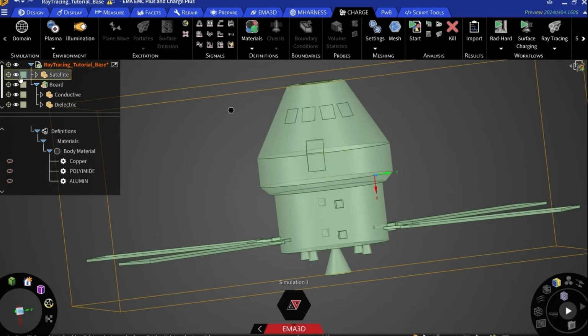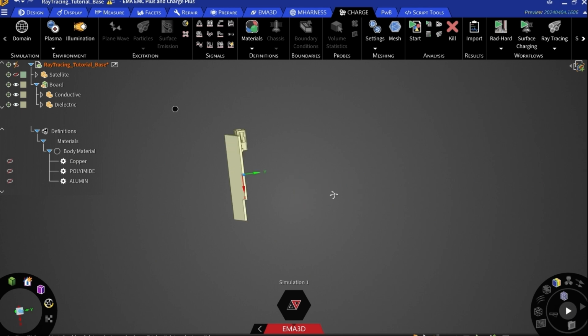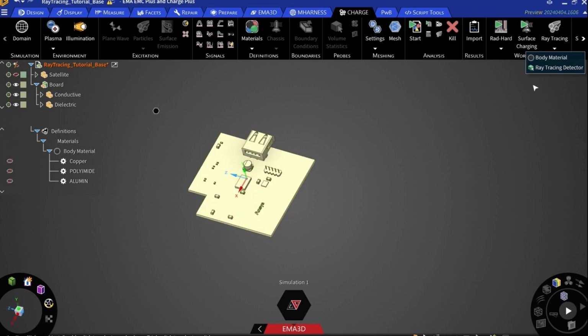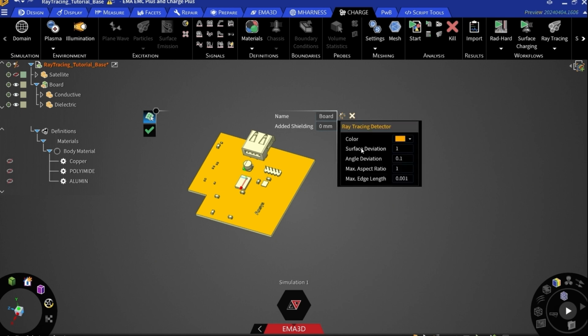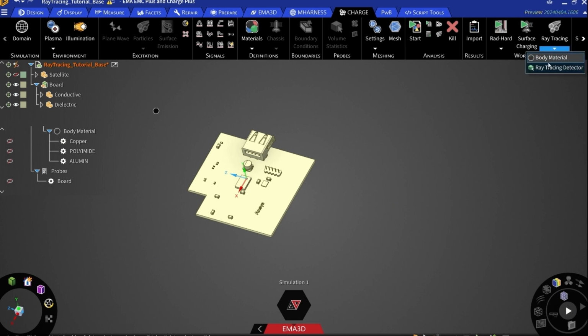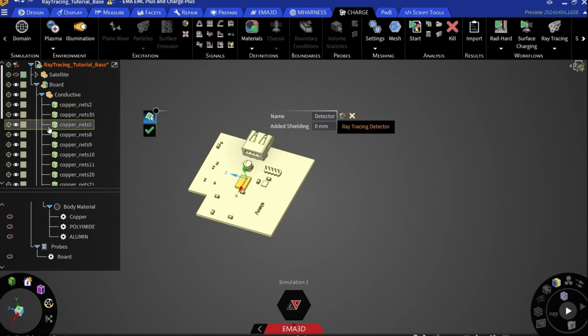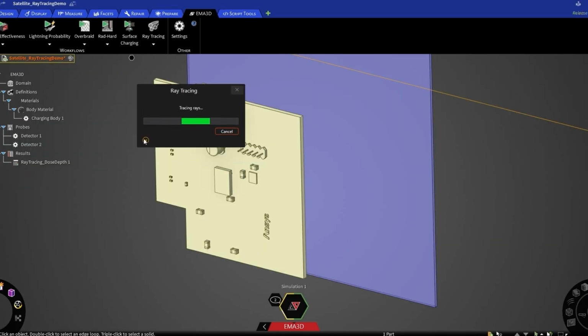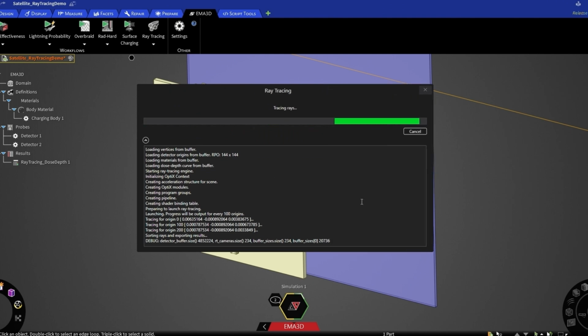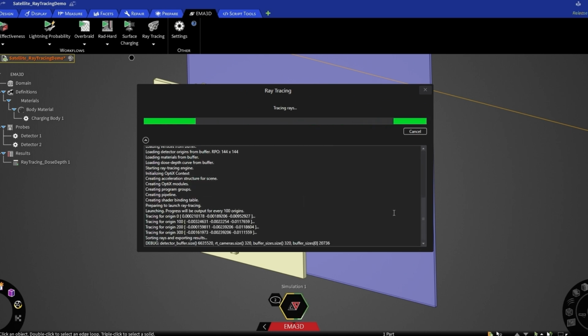In Ansys Charge Plus, we have the ability to model the PCB inside an enclosure and inside the satellite and understand how much radiation will make it to the component. We are using a ray tracing solution to be able to understand how much shielding there is between the PCB and the outside environment. Once we know how much shielding there is, we can use what we call a dose depth curve to extract how much dose will make it all the way down to the component.